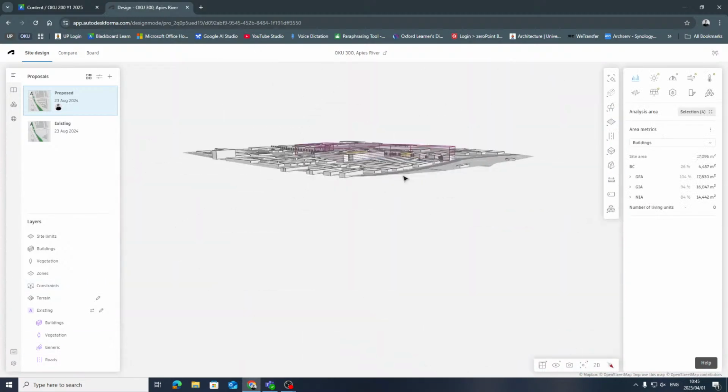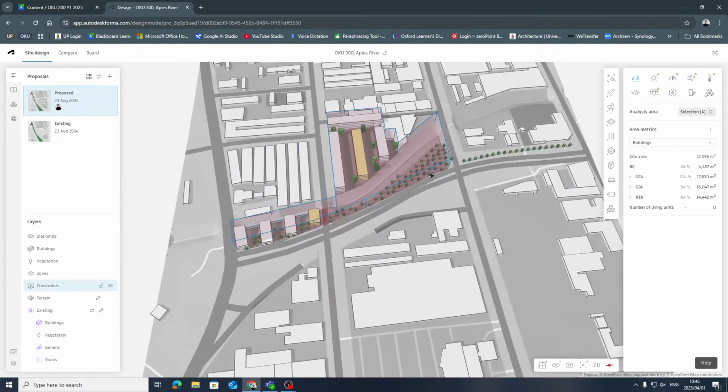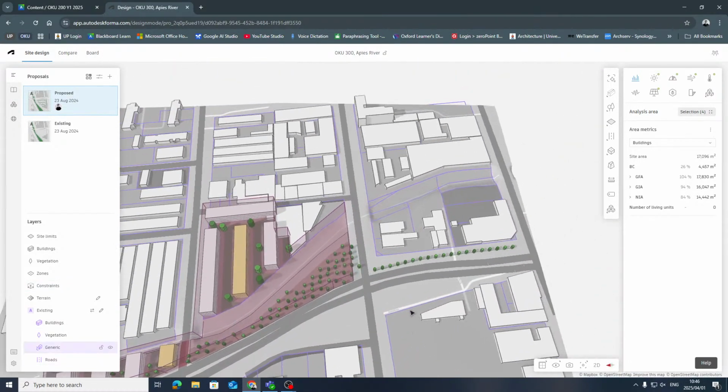All right, so what I would like everyone to do, I've got a bit of work to do on my side. I had a whole series of workshops pre-built that you would do in Formit. You'll model some timber details, and then you pull it into Revit and ArchiCAD, and then you document those details in ArchiCAD or Revit. Okay, because modeling these types of details in Revit is quite complicated because you've got to understand structural systems. It's a lot more complicated to model these types of little details in Revit and ArchiCAD. However, there are model in place options for both ArchiCAD and Revit that I now have to bring forward.